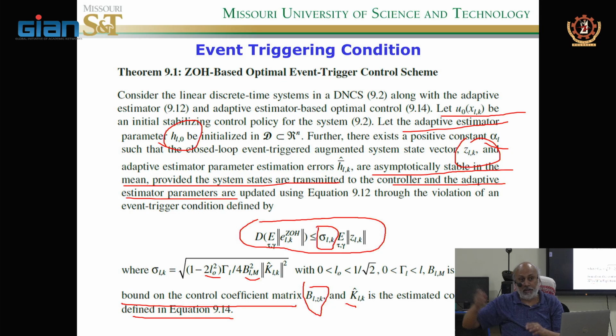Then we went one step ahead and said, well, we found out that you don't have to send data transmissions or the state vector and the control input every sampling instant, periodic sampling, because that also increases the number of data going through the network. So we use the event triggered sampling, where you can stretch the sampling instance. This way you have more bandwidth for the network and more number of subsystems can coexist. And that's the benefit of the event trigger control. You're still doing cross-layer design. Okay, any questions, guys?